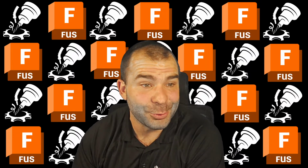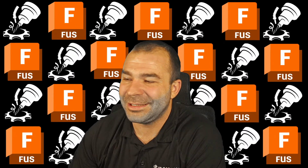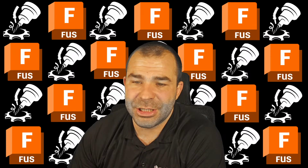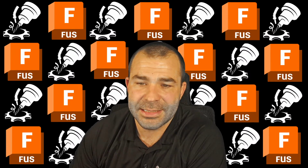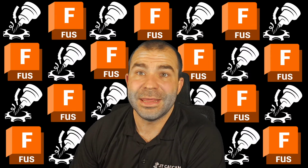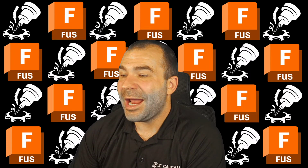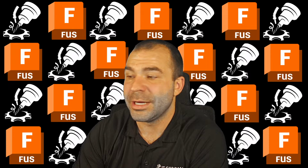So Brett, I know you quite well. We've emailed back and forth. The G154 is technically already there if using a machine definition, right? Now, if you're not using a machine definition, that's more than okay, guys. What's going to happen is your post actually has it in there by default, but you need to know the math on it, right? So in this case, I need to know that 1 through 5 is G54 through G59, and then 6 would be P1, P2, P3, and so forth.